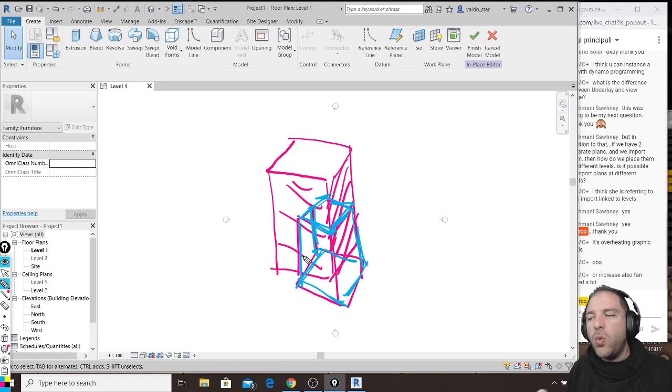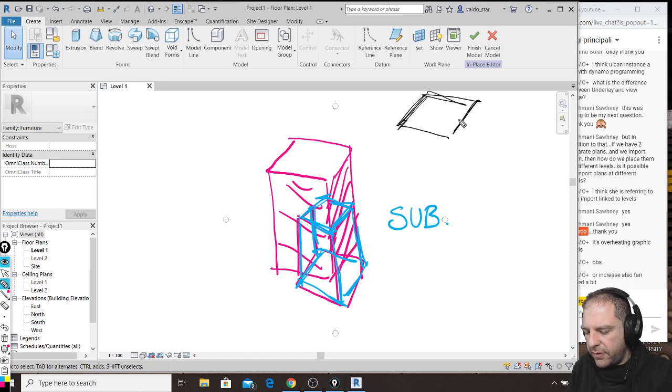extrusion, what void does is what we have already seen in 3ds Max, that is, it is a Boolean subtraction. So if you first make, let's say, an extrusion, and then you make a void extrusion that has volume in common with your solid, the final result will be to create an object that will be like this.